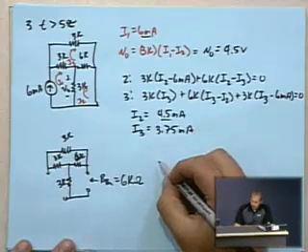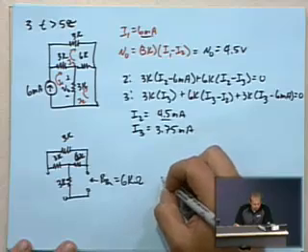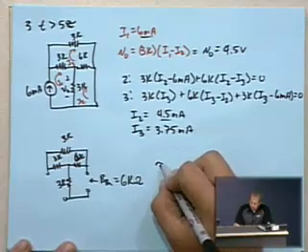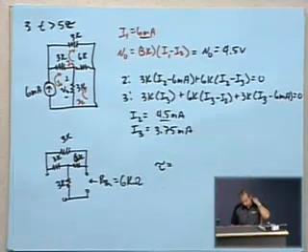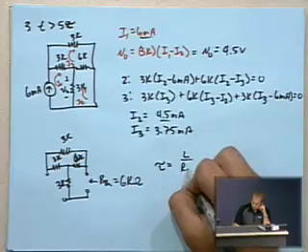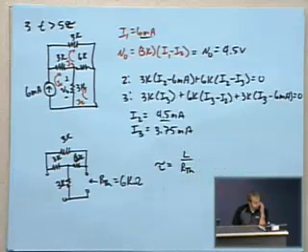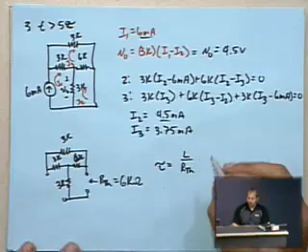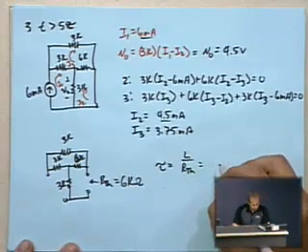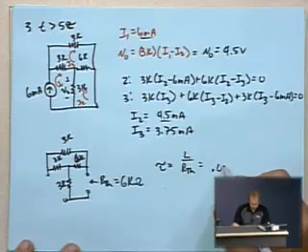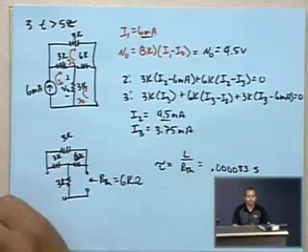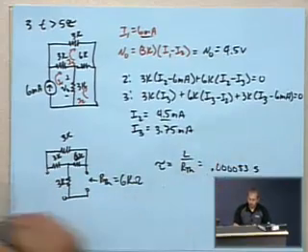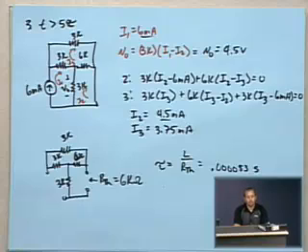Here's where I made another little mistake. I always forget that whenever I make these problems and I choose the value for the inductor, the time constant is L over R Thevenin and not R Thevenin over L. So this ends up turning into an extremely small number: 0.000083 seconds, when you plug in the values of a half divided by 6,000, which is a fairly large number.